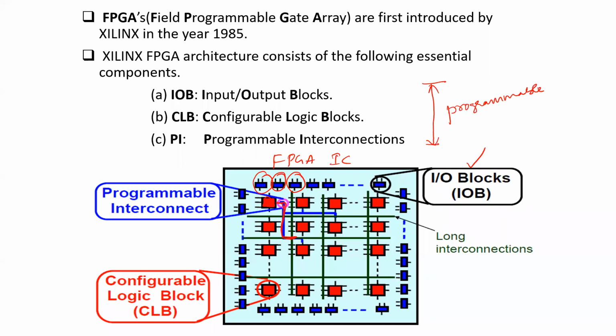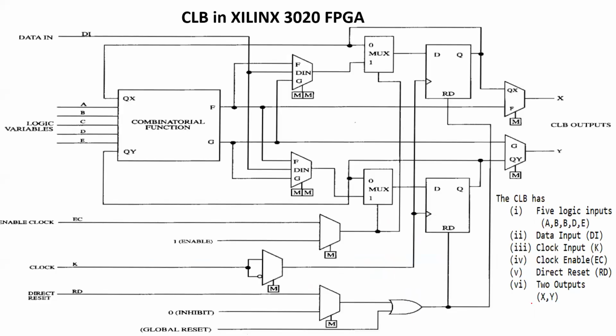What do you mean by programmable? It means we can set a particular component, access or control a particular CLB, according to the bit information that we are giving. Therefore the stream of bits that is necessary should be generated, and we have to give the bit stream information to the FPGA. The FPGA will configure to those bit streams, and it allows the use of the components available in the FPGA, right? Please remember these points very clearly. Okay, fine.